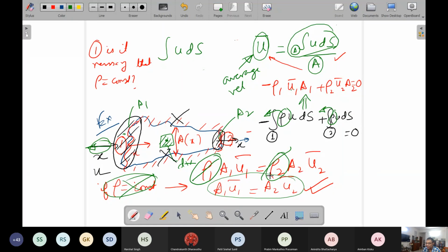Now I will try to arrive at it through an alternative approach by considering incompressible flow from the very beginning. So here we started with what? Can you remember? We started with steady flow, right? We did not start with incompressible or compressible. So that is how the time dependent term in the continuity differential equation was 0. With that only we started this derivation.